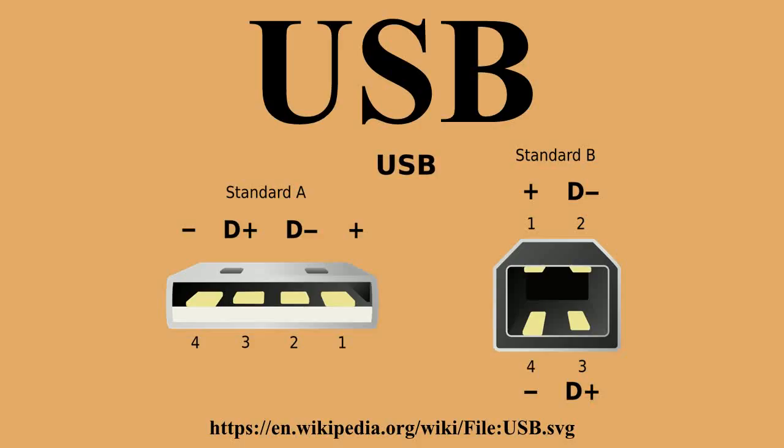The USB 3.1 specification takes over the existing USB 3.0's superspeed USB transfer rate, also referred to as USB 3.1 Gen 1, and introduces a faster transfer rate called superspeed USB 10 gigabits per second, also referred to as USB 3.1 Gen 2, putting it on par with a single first-generation Thunderbolt channel.